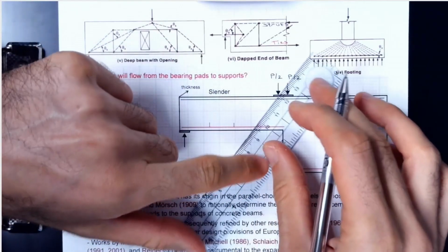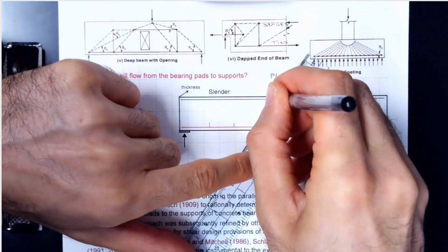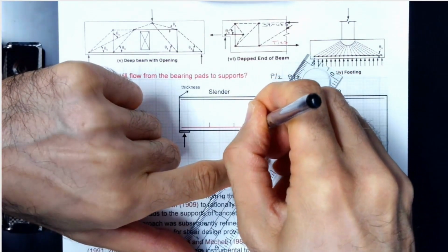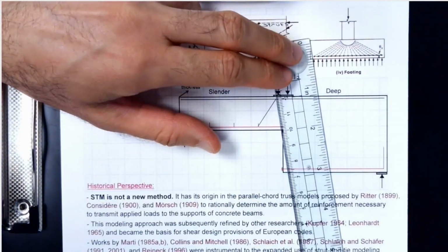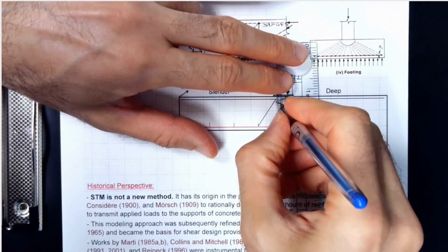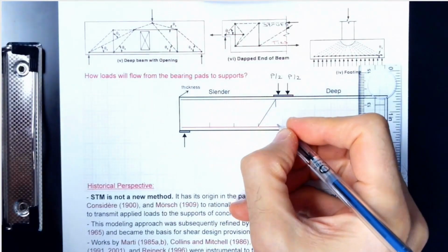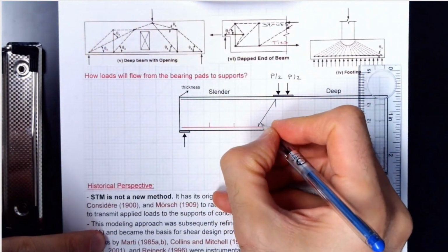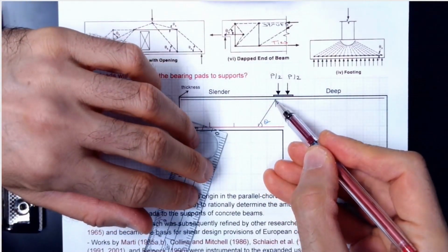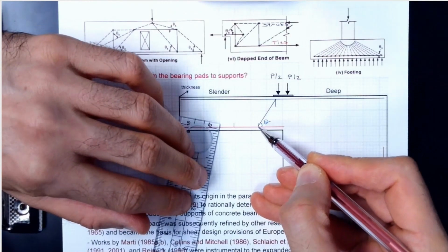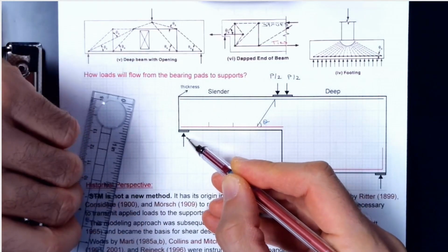So what you need to do for this one is to use straps. So go with a steep angle. Again, stress likes big angles, right? So angle is important. Large angle. When I say angle, it is, for example, call this angle theta. So you are shooting your compression with a steep angle, as steep as possible. It's going to make it much better, but now you didn't reach the support point, right?